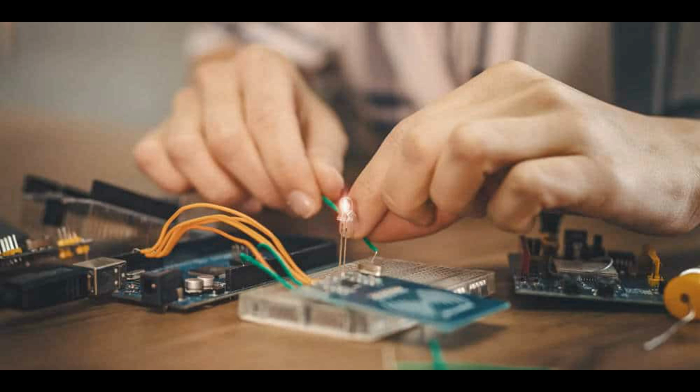Preventing short circuits. Solder mask helps prevent unintended electrical connections or short circuits between adjacent copper traces or pads. It does this by covering the areas of the PCB where soldering is not intended, ensuring that solder only adheres to the designated pads during the assembly process.